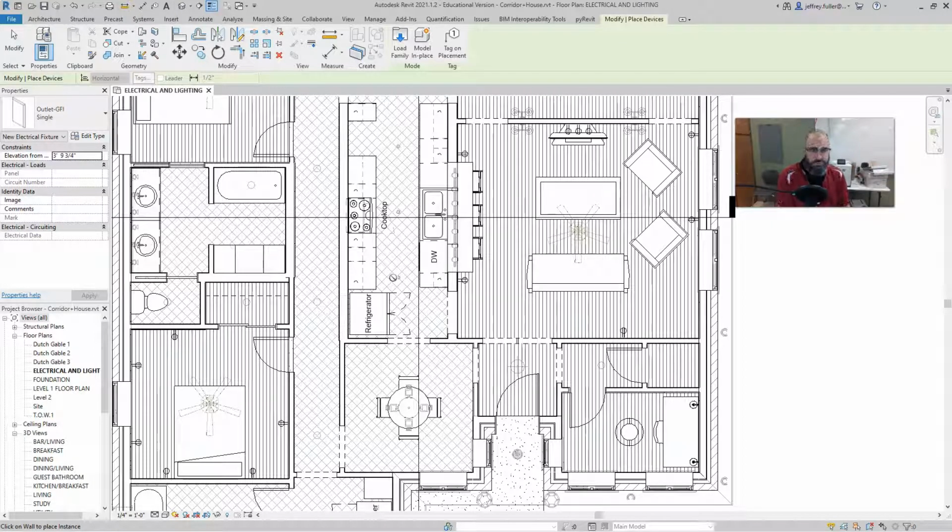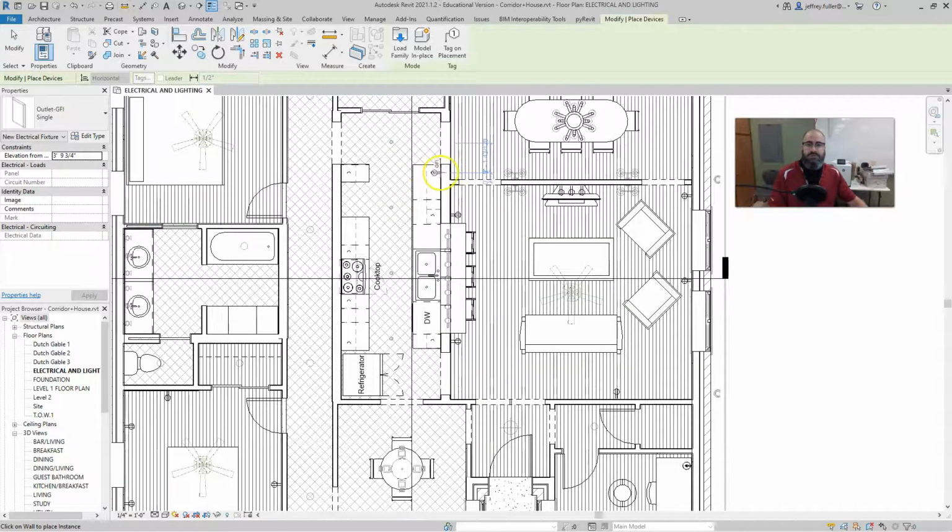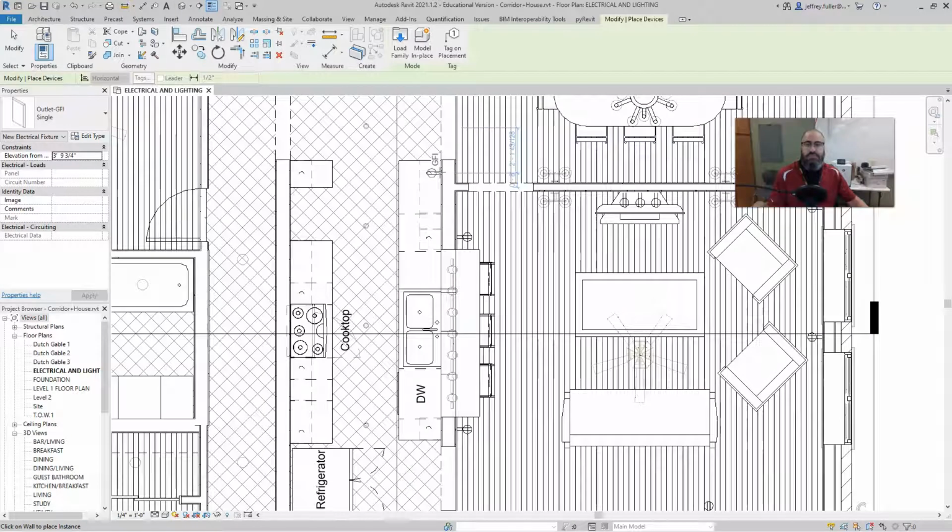You want to be within 1 foot of an obstruction, such as a corner, and you want there to be no more than, I think, is it 24? I think it's 48 inches apart, but you'll actually put more than that in there. With today's environment of all the technology that we have, all the electrical things, especially in a kitchen, you've got toasters and mixers and several types of mixers and processors and bread cookers and all kinds of stuff, crock pots, you name it. So it's really good to put receptacles just about anywhere you can think to put one.